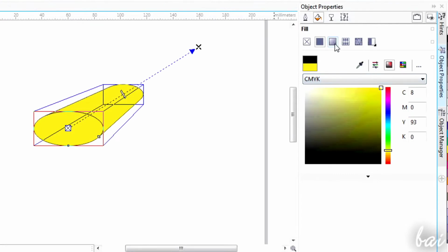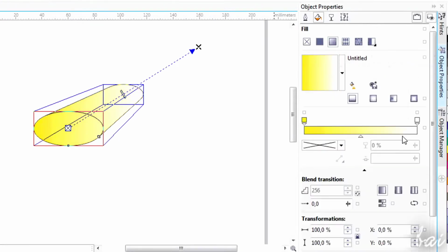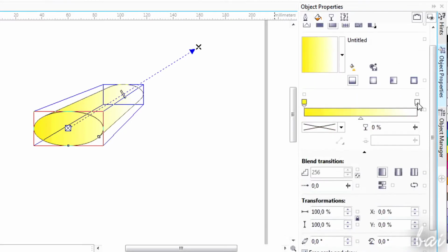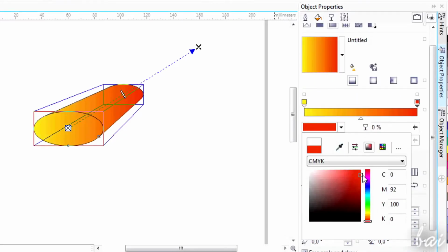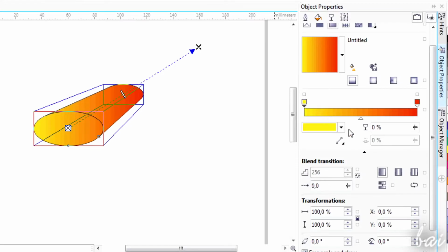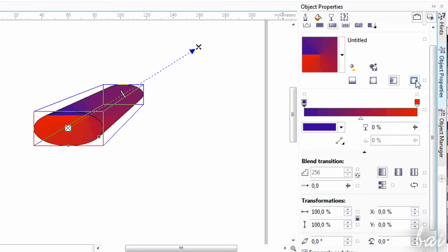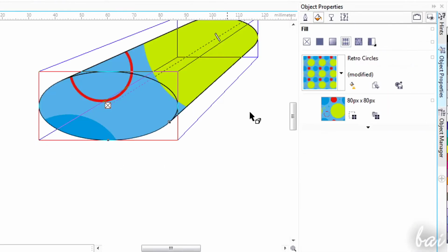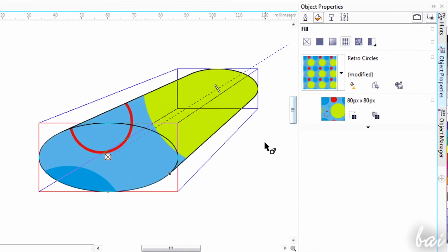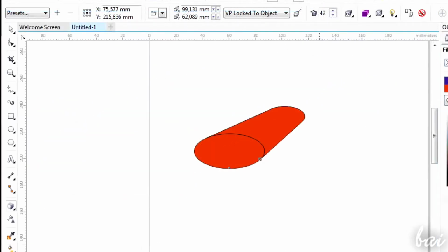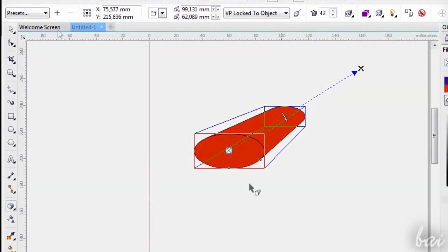Mind that the 3D object you created is always a 2D object according to the software. In fact, if you apply any gradient or pattern on the object, this will be distributed in the same way on both object and extrusion. To personalize your object without losing its 3D shape, you need to use the extrude options on top that appear when the Extrude tool is on.